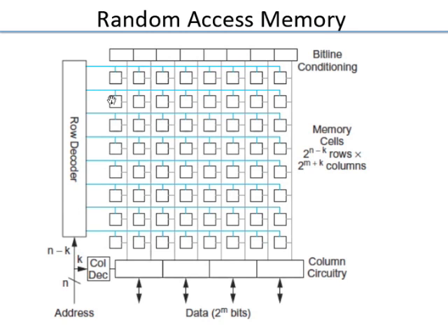So there are 8 rows out here, and he is taking out 4 bits. There are 8 rows and 8 columns. So you take 3 bits to select a row, and you decode it, and you activate one of these horizontal lines. Those are called word lines. You activate one of them.